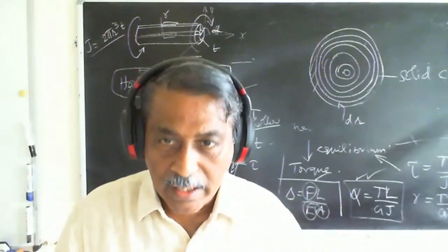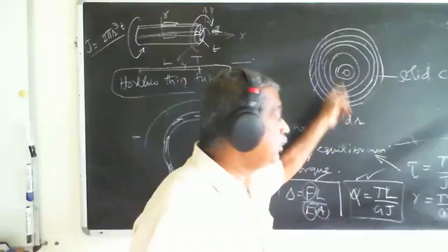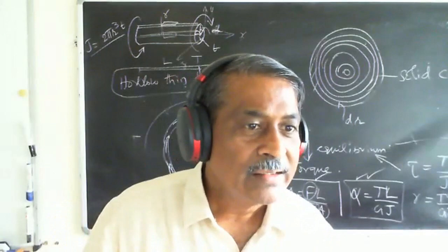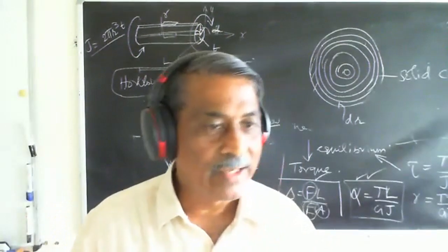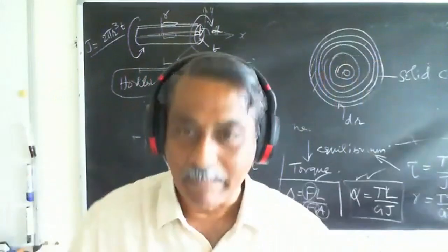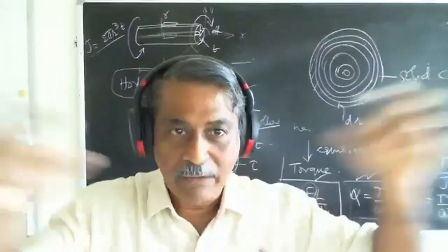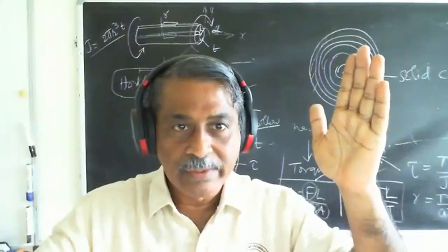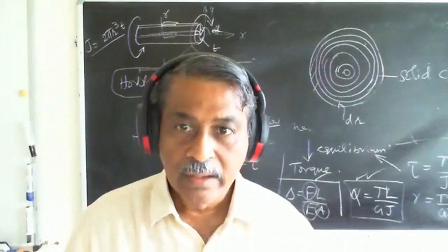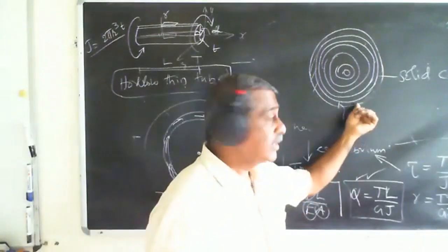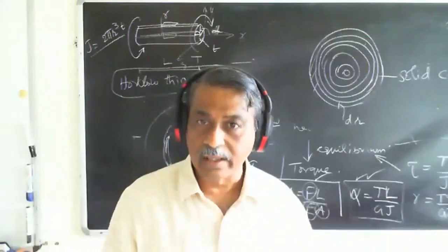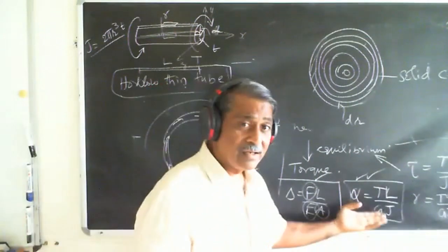So, and therefore, what do you know about the individual tubes here that you're summing up? Theta should be the same for all. Fantastic, Bindu. Correct. The end displacement is the same. Do you remember when I have two rods and the end displacement is the same, then I sum the two to get the stiffness, right? So if I get the stiffness for each one of them, I can add the stiffness for all of them put together, correct? What is stiffness here in this?